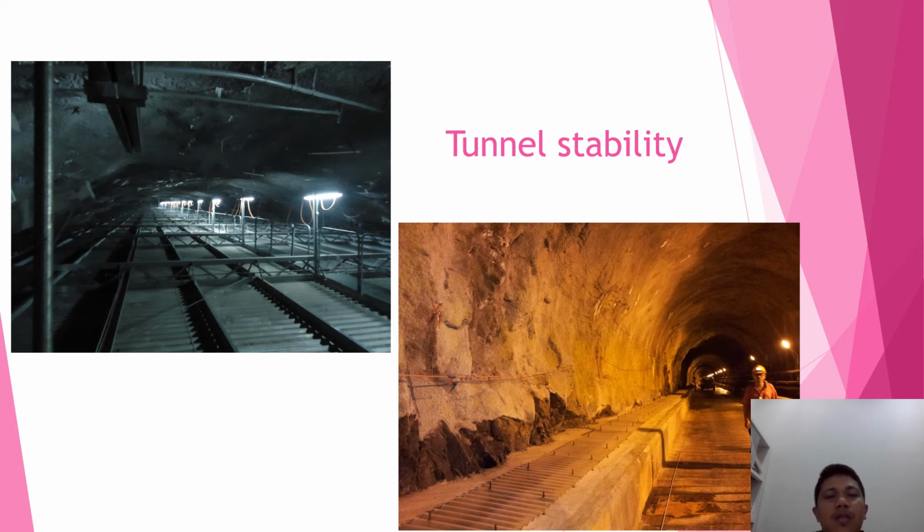a tunnel stability study. If you can see here, we laid out the cable on the crown of the tunnel, and then we drilled the left and right sides of the tunnel in this area. We tried to look for where the high water content is, which we can relate to maybe less stable areas. So we used the resistivity method last time to help engineers design the tunnel stability method.